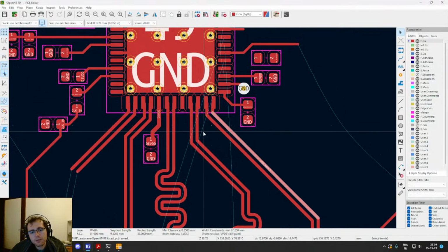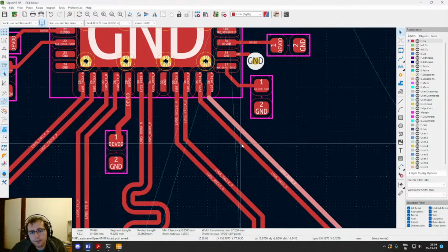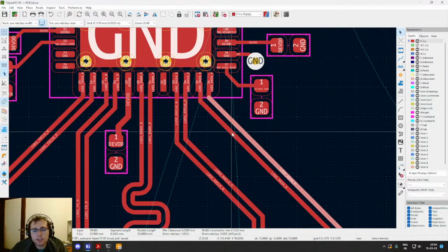The big advantage of having LVDS pairs compared to basically any other single-ended way of doing it is that it's less prone to noise, because what is important is the voltage difference between the lines and not the absolute voltage of the line. If you take, for example, an SPI bus and you have a perturbation on the line and the voltage changes at the moment where the MCU samples the line, then it's going to see a bad sample and corrupt your data.